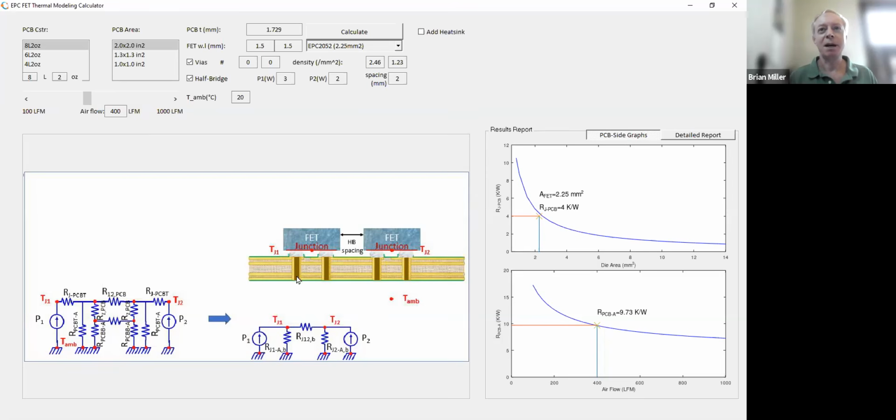The thermal conductivity is dominated in that case by the walls, by the copper and the walls of the via. And it was found that by going to conductive fill, the conductive fill isn't as good as copper. I mean, it's okay, but it's not great. So there's only minimal improvement.